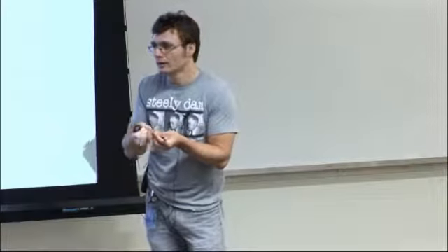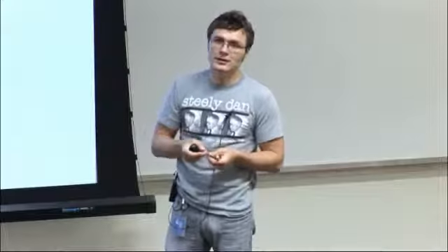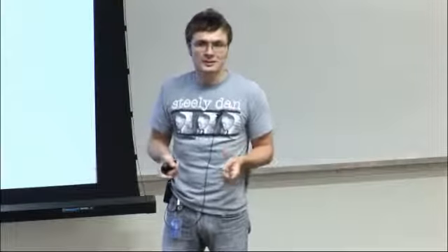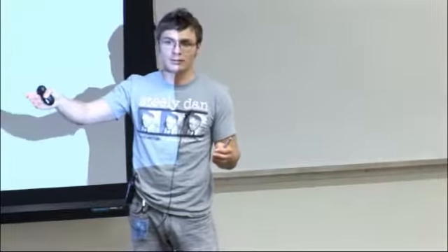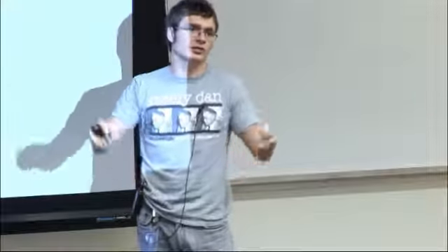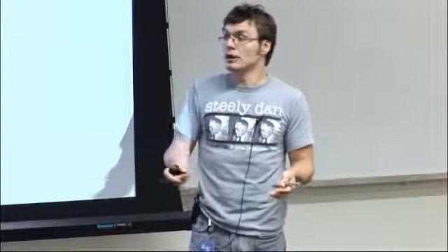So we had a lot of trouble with the repeatability of these transducers. Sometimes they don't work as expected, so you need a more reliable source of ultrasound, and that's more wideband, okay? Because these things are very narrow band. It's 40 kilohertz and a bit aside. So we need to push things a lot, right? Maybe you'd like to have something that has a much wider bandwidth, and these things exist.